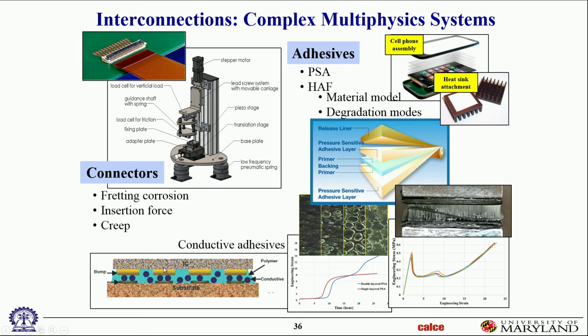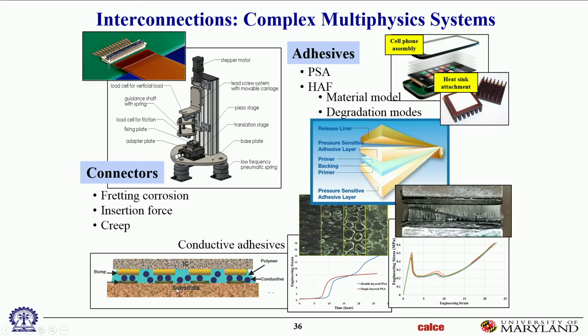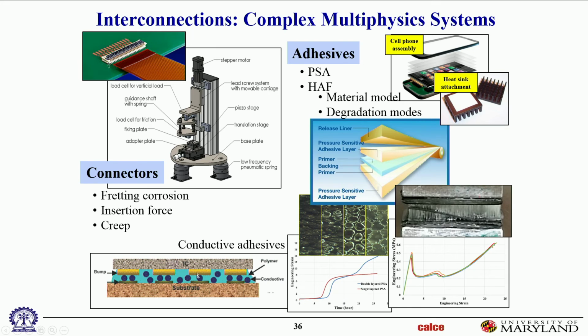And the idea is here you're making electrical contact. So you have the substrate, you put down the polymer adhesive, the conductive adhesive, which is filled with these conductor particles. You put the chip down and you just glue it together. Then you cure it, it just glues together. And now these conductive particles in between, instead of solder joints, are giving you the electrical connectivity. Of course, the conductive particles are here too, but there's nothing to connect to, so it's fine. The problem is if you get enough conductive particles going laterally, now you have a short between neighboring pads, and then you have a problem again. So you have to carefully control the density of particles you have given the pitch size between your neighboring pads. Okay, so that's one kind of polymer.